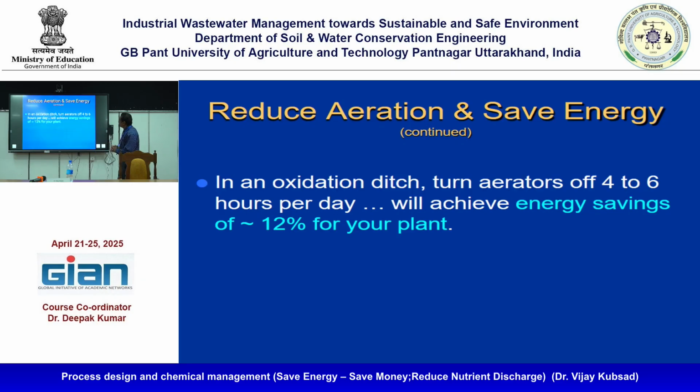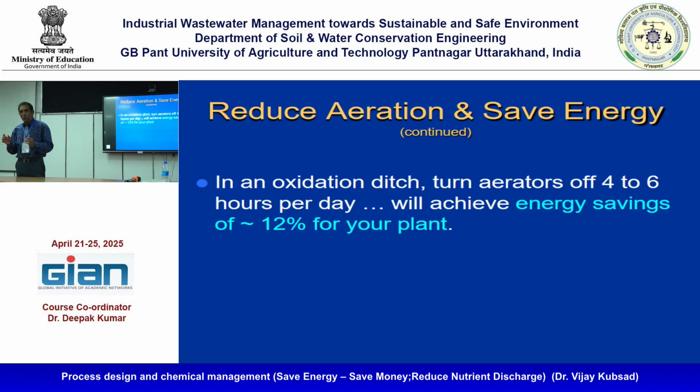Some percentage. In an oxidation ditch, turning the aerator off 4 to 6 hours per day will achieve an energy saving of 12%. How did this number come? I did a series of studies. We are going towards saving money, right? That is also important. But our main focus is quality. Once quality is achieved, then we look at how we can reduce the cost.